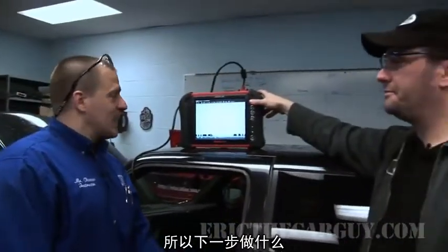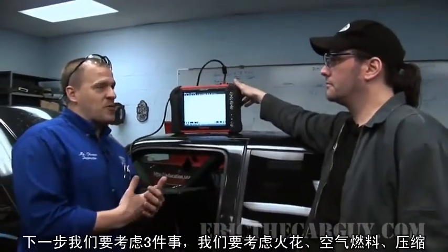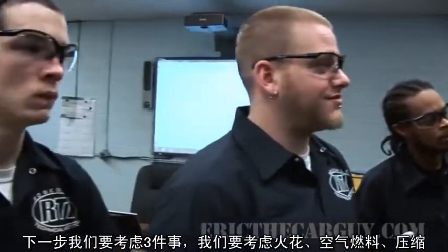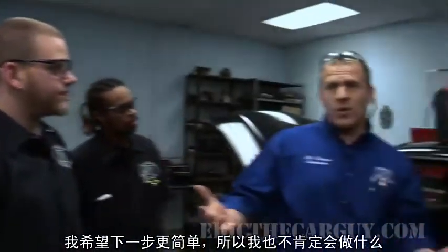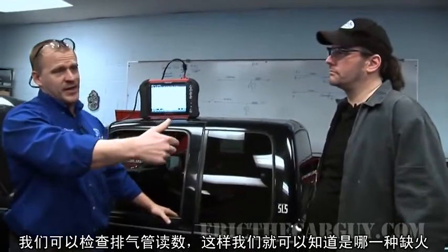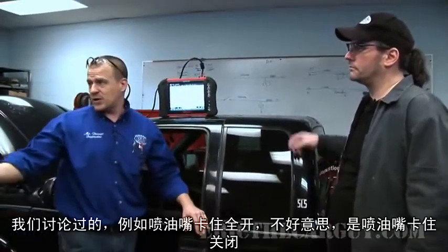So what do we do next? Next thing we got to think about are the 3 things, right? We've talked about this, guys: spark, air-fuel, compression. We're missing one of the 3, and I'm always looking for the next easiest step. I'm not sure where this is going to go, but I brought a couple pieces of equipment out. I brought a gas analyzer so we can check tailpipe readings and see what type of misfire. We talked about that, right?